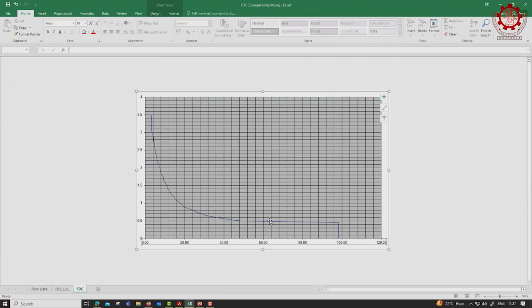Or, another way of deciding this is to select maybe 3 or so rated flows, theoretically design 3 plants and estimate their project costs, and then do a financial analysis to see which rated flow will bring the highest return on investment. If you go by IRR, see which will bring the highest IRR, and then accordingly decide the location on the flow duration curve where you should have the rated flow, right.